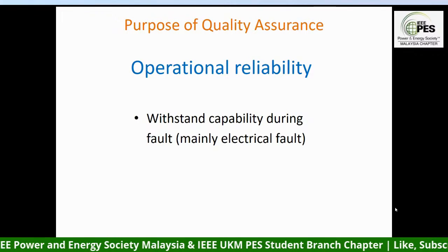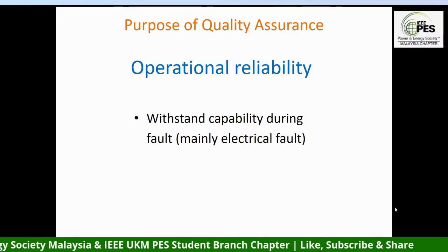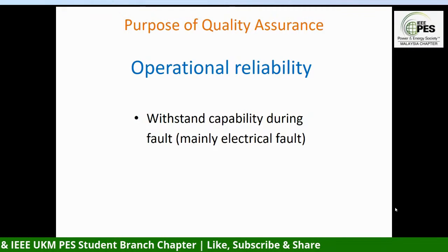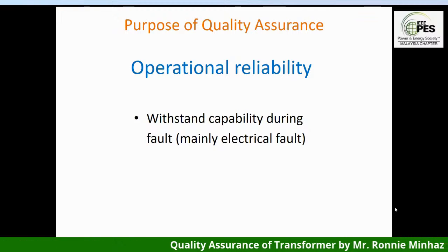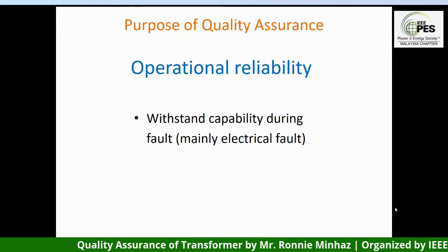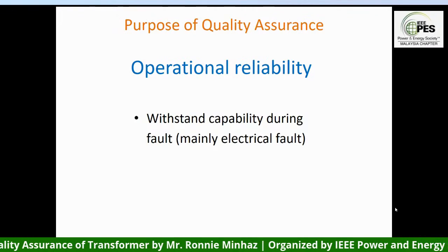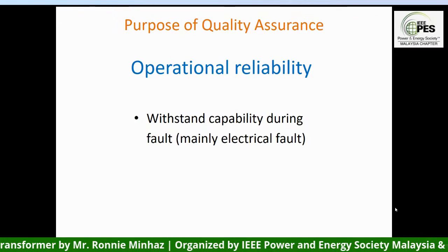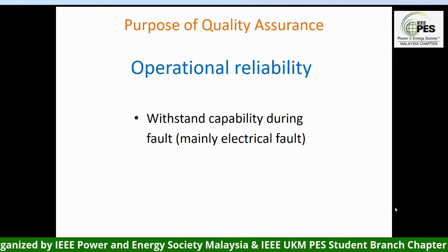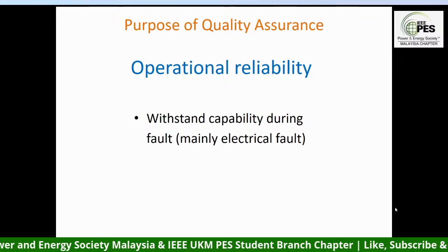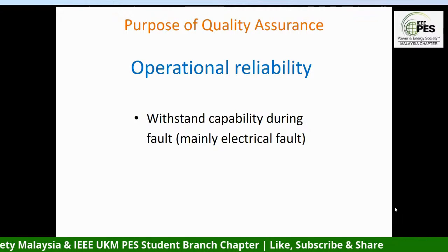So that's why, at that time, those transformers were designed, especially, over designed. Not only over designed, they're also overbuilt. If you go to any substation and look at the transformers from the 50s, 60s, 70s, even up to the mid 80s, you'll see they are big, bulky, and heavier, and they're over designed. That's why when the rise of the throughput happens, they are quite strong enough to withstand those faults.